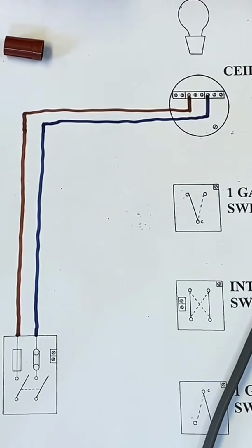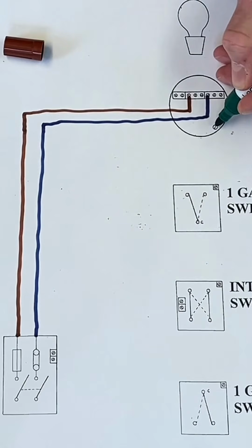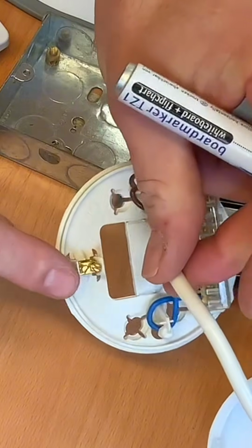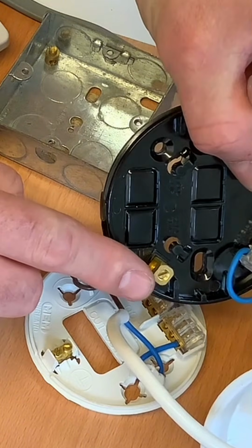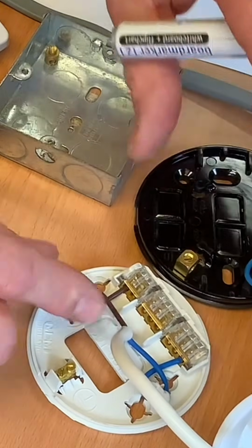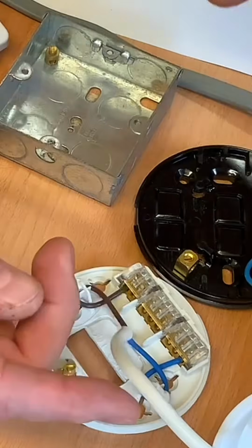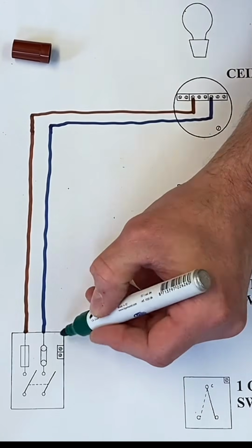Gaz can do it. There you go, so that's our neutral connection in, and then our CPC comes out of our consumer unit, out the earth terminal, and is going to come into this terminal here. We look here, there's 2 on this one for our CPCs to go in, and on this make, there's just the 1 CPC terminal. Remember, we've talked about it previously. All the accessories in the workshop we're going to be working with are plastic, including the boxes. The CPC is there in case we change it for an exposed conductive part.